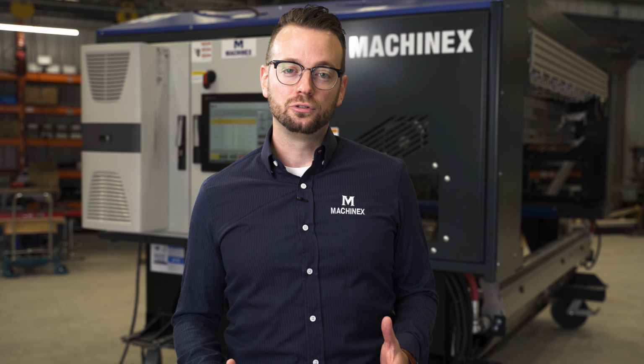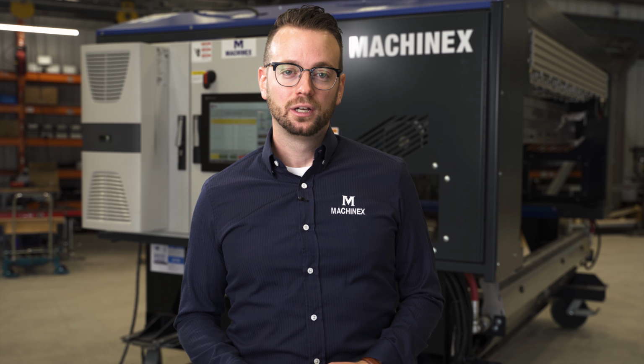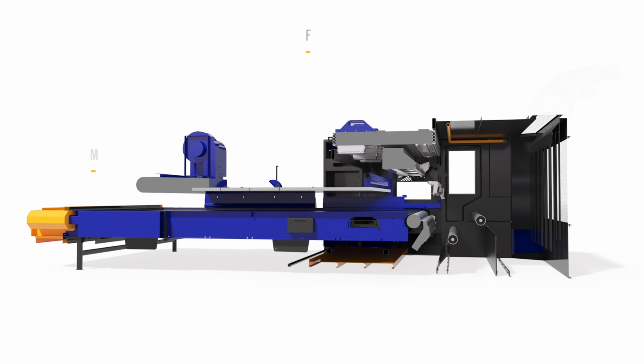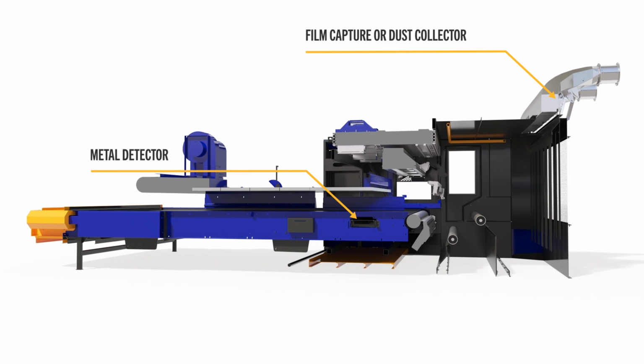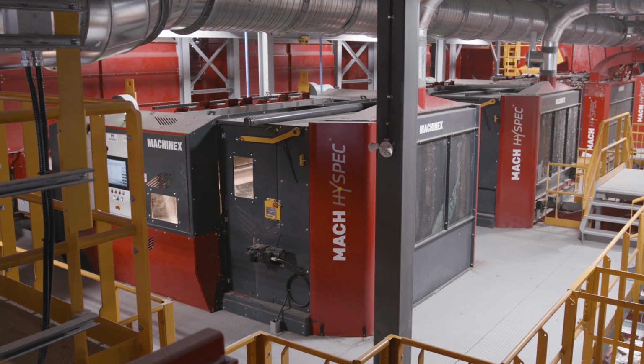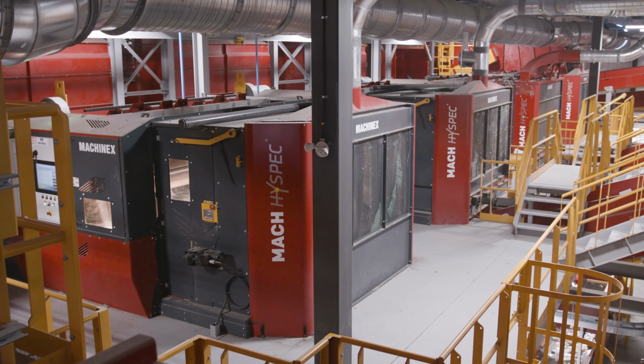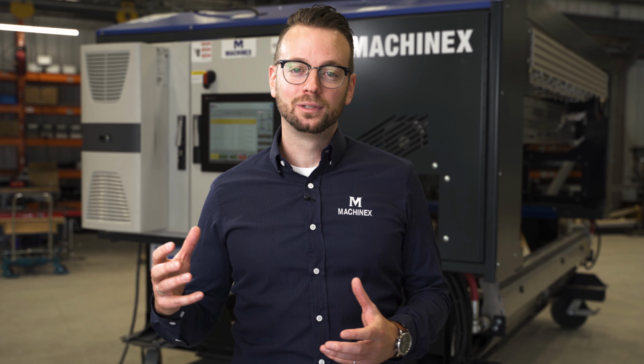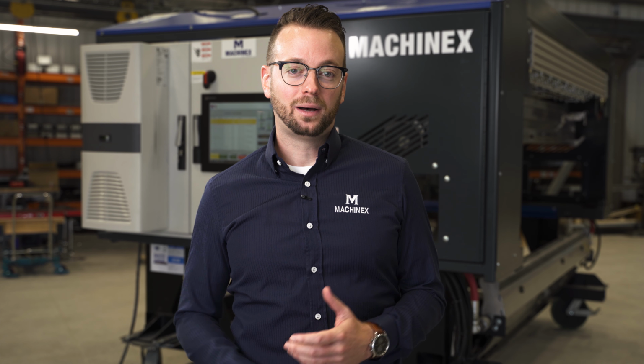So a metal detector uses inductive sensors to recognize, identify, and ultimately eject the metal content of a stream. The third option you can find on this machine is the provision of a film capture device or a dust collector device, which is installed on top of the ejection hood. The objective of that third option is to vacuum the plastic film that will be floating in the ejection hood just fired by the optical unit, or vacuum the dust that will be generated by the optical unit.